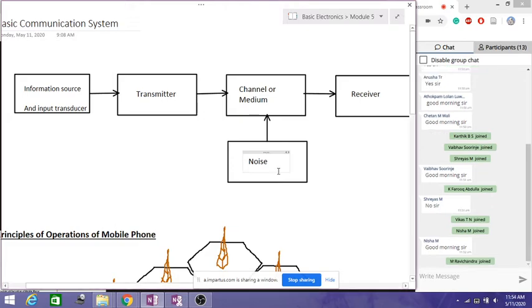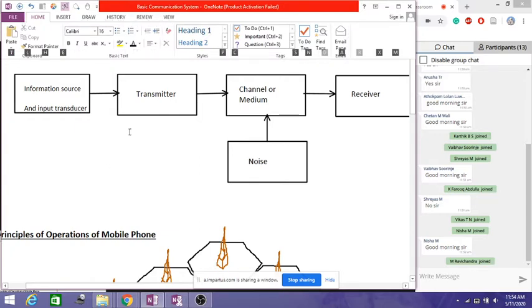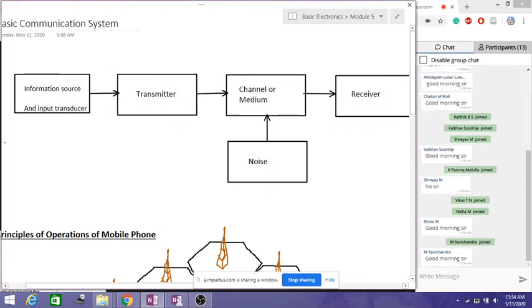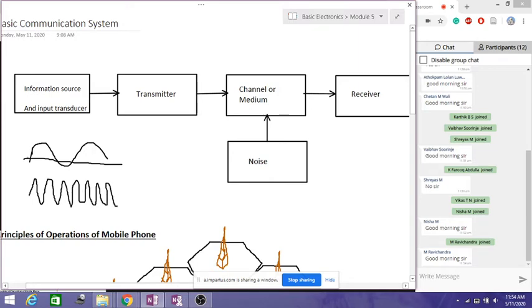If we talk about a communication system here, for example, if my source is a sinusoidal signal, something like this, this is my modulating signal, which we call the information signal. If I want to transmit this information signal, I have to put it on a high frequency carrier. This we call the high frequency carrier. Because the speech signal is of low frequency, it cannot be transmitted a longer distance just like that, because we would require a very tall antenna to transmit these low frequency signals.